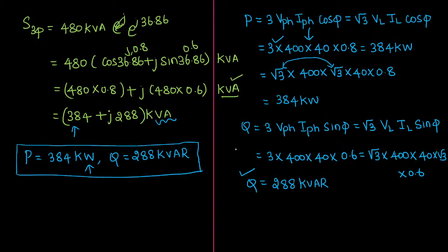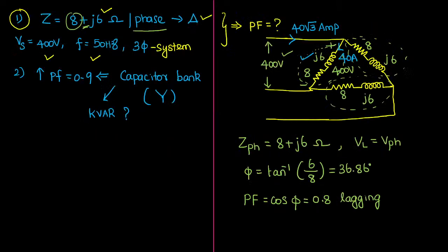Okay, sir. Now, is there any other formula to calculate? See, let me prove it. Come back to the network. If you observe, the resistance offered per phase is 8 ohm. Yes or no? Now, the real power consumed per phase. I would like to calculate the real power consumed per phase, or only by that 8 ohm resistor. I am just focusing on it. How will you calculate? This can be calculated with the help of I square R or V square by R. But remember, these are per phase quantities because I am individually focusing only on this 8 ohm resistor.